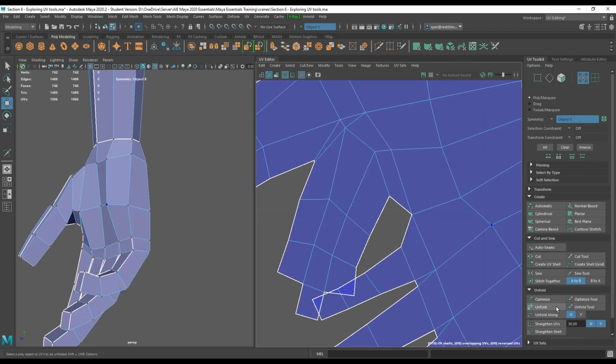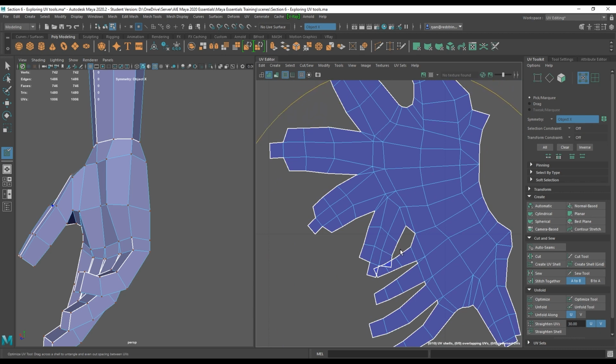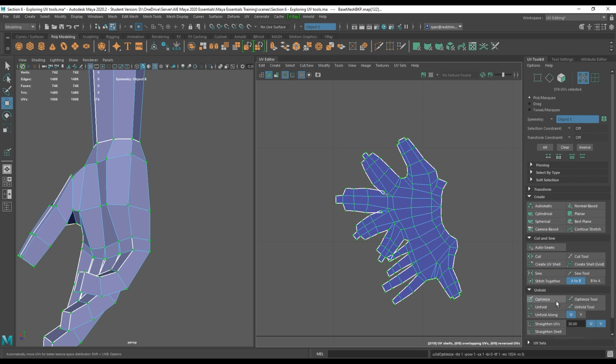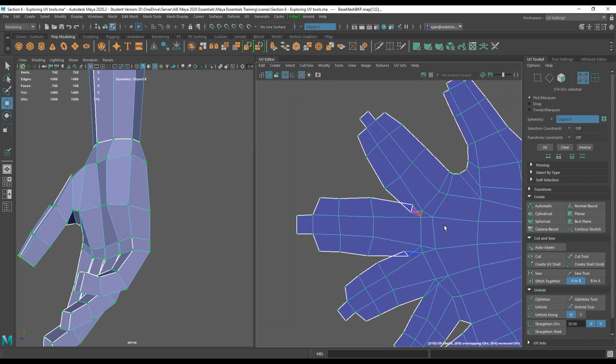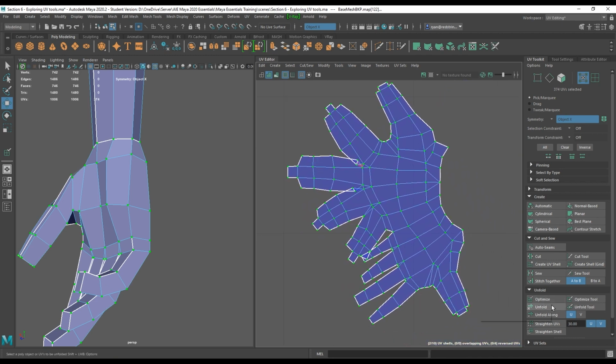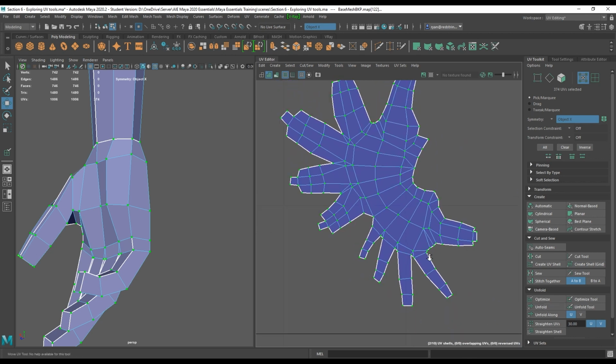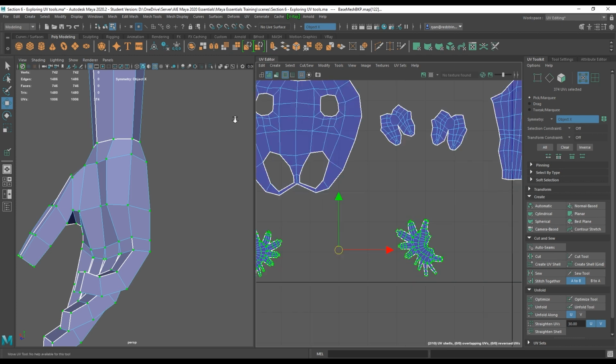And then we can use the optimize tool, for example. Now as you can see it's a big brush, and holding down B, middle mouse click and dragging, I can change the brush size. And now as I paint, you'll see Maya trying to optimize the UV island, and there it's overlapping, so that's causing more problems than anything else. If I press W, select all the UVs, we can just click optimize, and Maya will optimize, but again it's overlapping UVs and stuff. So that's why I like just doing the unfold, and Maya makes sure that there's no overlapping UVs and all that kind of stuff.